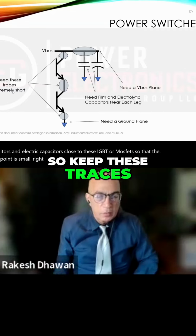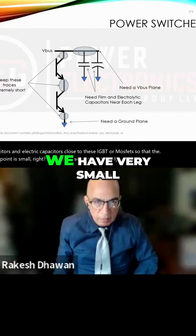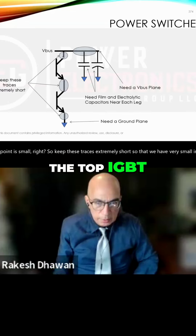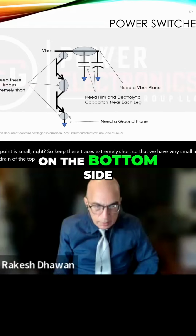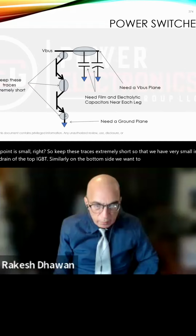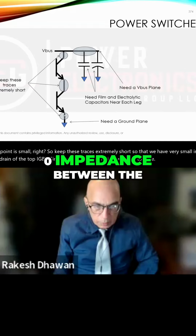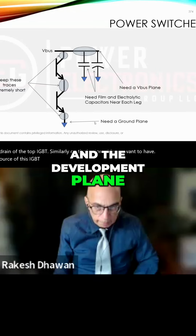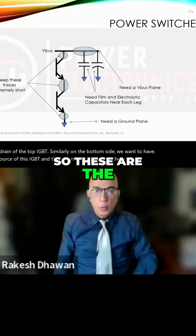So keep these traces extremely short so that we have very small impedance between the V bus and the drain of the top IGBT. Similarly, on the bottom side, we want to have zero impedance between the source of this IGBT and the ground plane, right? So these are the important rules.